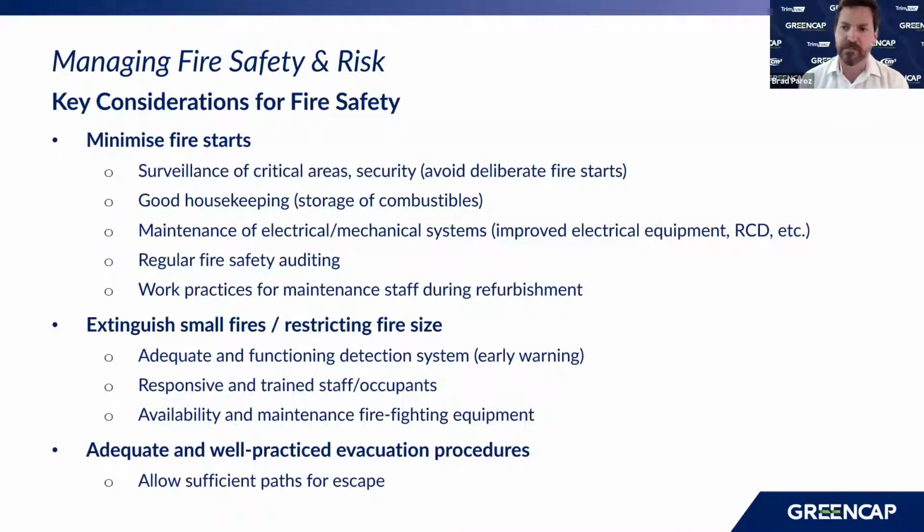Yeah, great. Really good point about the building fire safety regulation arising from the Childers Backpackers hostel fire. Most fire safety legislation and BCA improvements are highly reactionary, and they are a direct response to major incidents. That's a great example of one. Combustible cladding is another. Sprinklers in aged care facilities is another, following the Quakers Hill fire in New South Wales. So, plenty of examples of a reactionary approach to fire safety by the regulators.